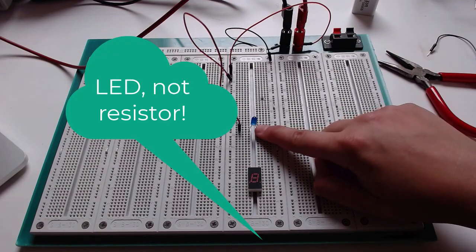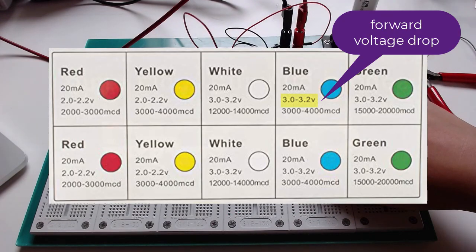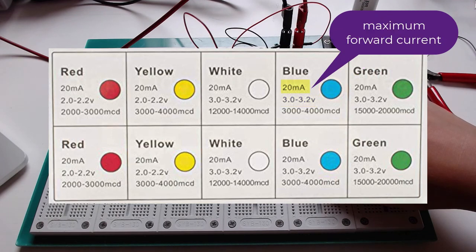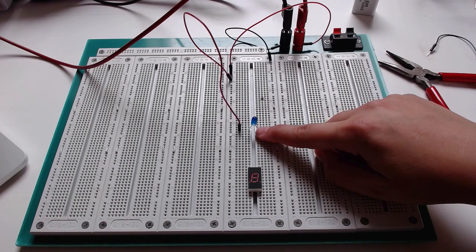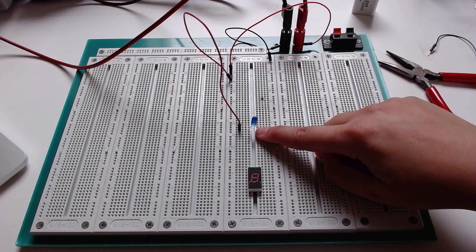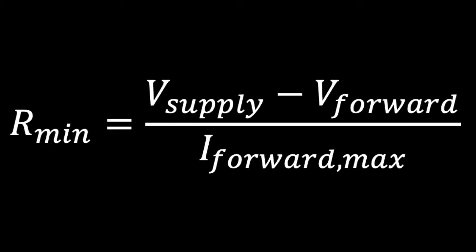So this LED has a forward voltage drop of 3 volts from the data sheet, and it has a maximum forward current of 20 milliamps. That means I can give this thing continuously 20 milliamps and it's going to be good. Any more than that and all bets are off. At some point this thing is going to fail. So what I can do is use the equation that the supply voltage minus the forward voltage drop, divided by the maximum current, is equal to the minimum value of our current limiting resistor.